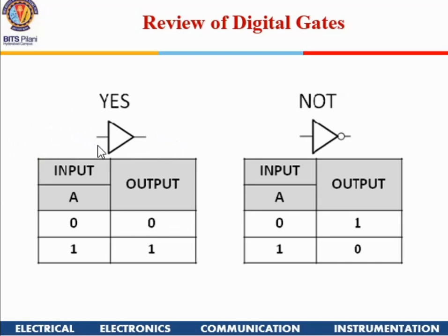So it is like an isolation between the input and the output stage. It will have high current carrying capacity, because if you have to transmit some data between two chips, there will be a physical line drawn and a lot of power will be required. So you can have a buffer, which will isolate the input and output.